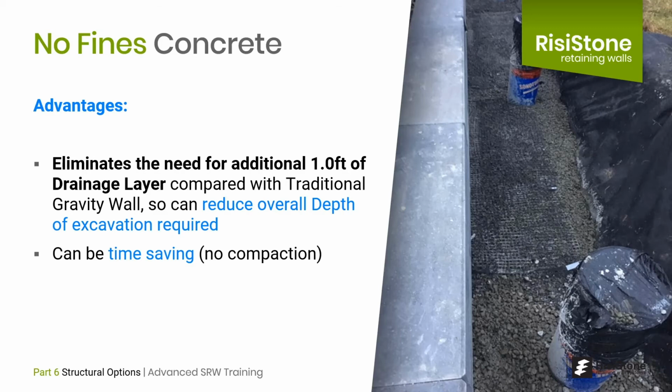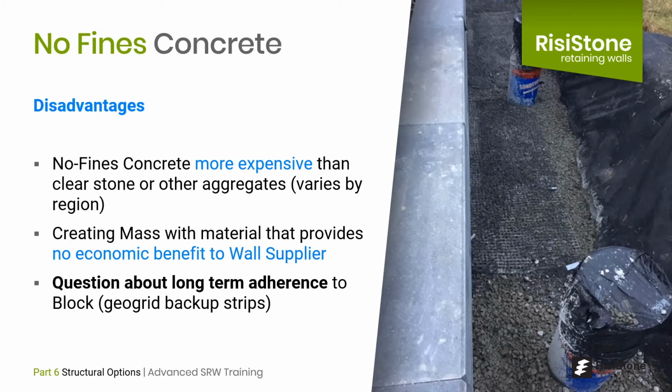There are also some disadvantages with no-fines concrete, the main one being price. No-fines concrete will be 2 to 3 times the price of regular aggregates, but I've found that this varies considerably from region to region. But if you consider reducing the amount of excavation required and the effort and labor to compact and fill regular aggregates, it may work out to be still more economical.